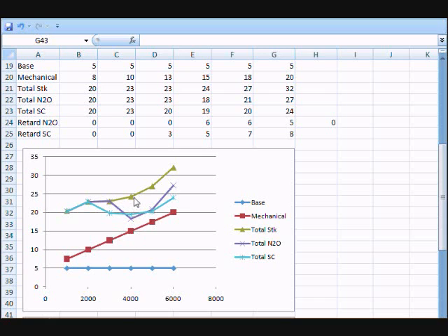For the nitrous injected car, peak VE is also at that same point because this is where we release the nitrous shot. And for the supercharged car, we actually see a wide range where we have good volumetric efficiency between 3,000 and 5,000 RPMs, but in the top end, the car doesn't make as much power as it could if this efficiency were flat, but because we lose volumetric efficiency above 5,000 RPMs, the car is a little down on power, and that means we can advance the timing a little bit to make up for that loss of